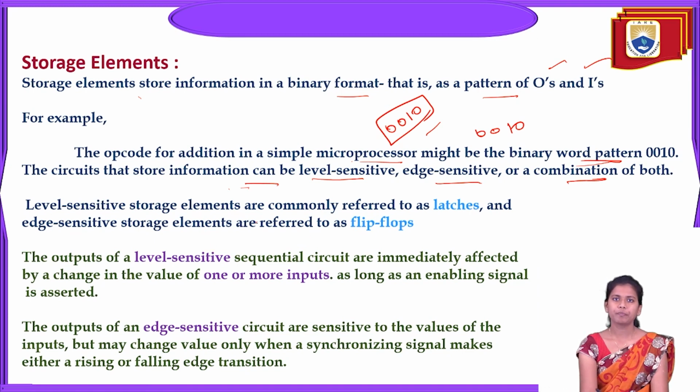Level sensitive and edge sensitive refer to signal processing based on latches and flip-flops. Why? Because latches and flip-flops are storage elements. They store one bit of information.